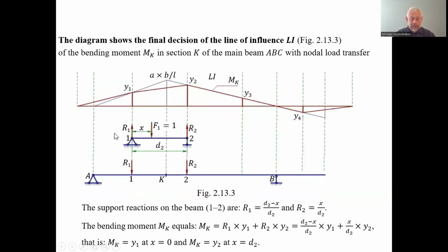So the moment of unit force, we assume that this unit force acts on the main beam in the point K; if the force acts here, the total force acts here. So the moment here will be equal to y1, and due to this the second reaction R2 will be 0 if the unit load is located only in the point of the node 1.